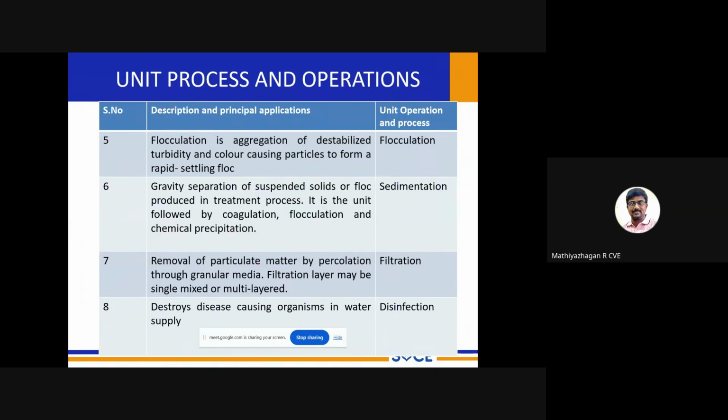During the flocculation process, all the microflocs attach together and form macroflocs, which are readily settleable. These macroflocs are readily settleable along with discrete solids. The raw water already contains discrete solids also. Discrete means they have a very high specific gravity, more than the water, so they are readily settleable when we stop the flow. Once we convert all the colloidal solids into macroflocs, we move to the sedimentation process, where we can settle down all the discrete as well as flocculent solids or flocs.